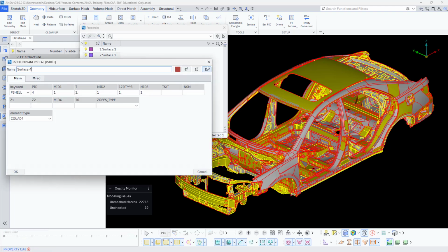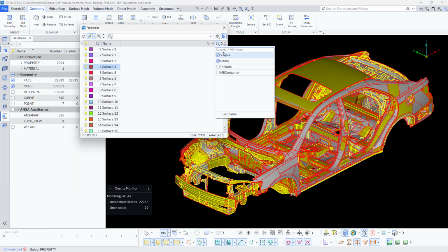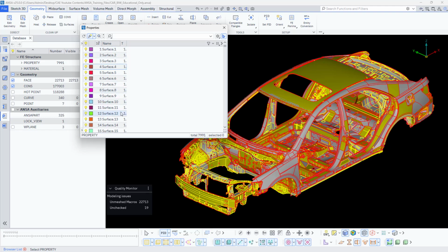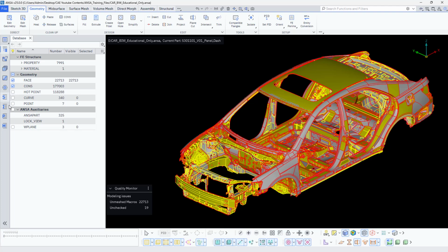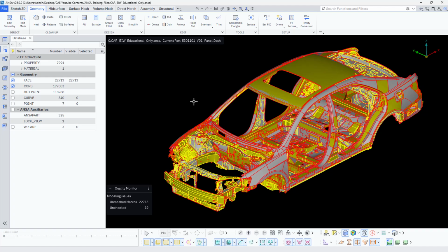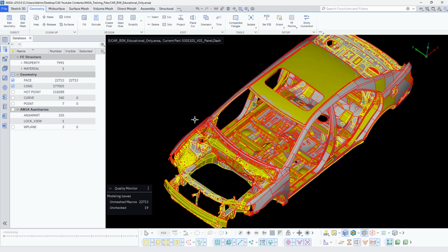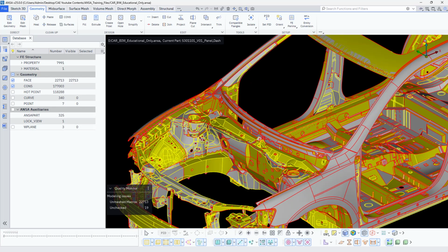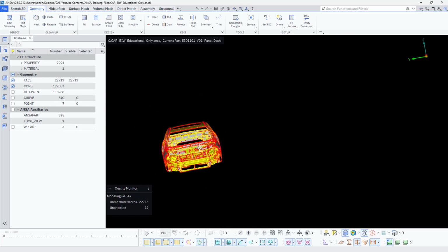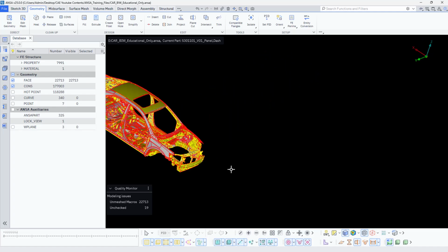You can see the property details. You can use this filter. Let's say I would like to see the thickness. You just mention T here, activate this, and it will show the thickness of all the PIDs. Similarly you can explore all these things later on, but right now not needed. So let us jump into the basic ANSA working. Now let me take you through simple geometry cleanup activities.